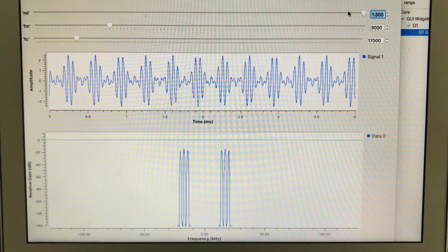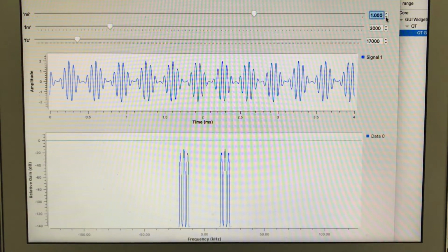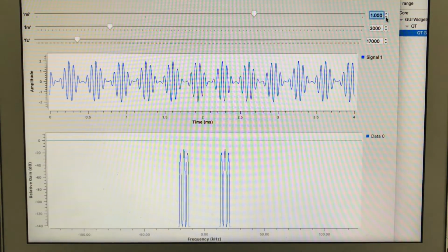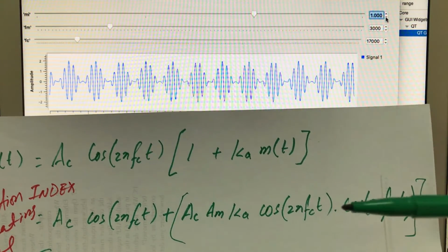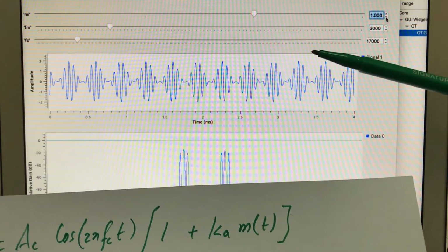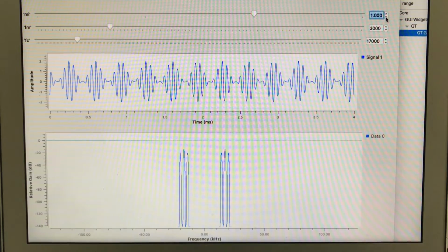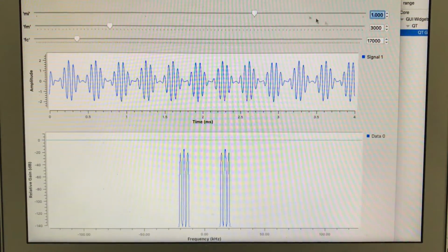So this is the idea behind how you can actually, by connecting your USRP or HackRF, transmit this tone in air. This is how easy it is to transform a mathematical equation from your book into a working system that will help you prototype different types of radios using GNU Radio Companion and software-defined radio.